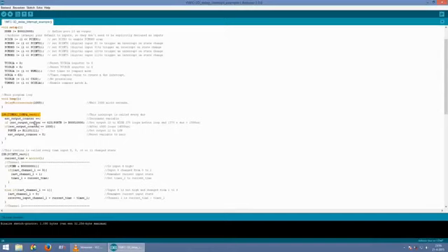Now in this subroutine, a counter is incremented. When it reaches 625, output 12 is set high. 1500 microseconds later, the timer reached 1000. Now the output is set low and the timer is reset. Now I don't go into the details because I just want to show you the results on the scope.